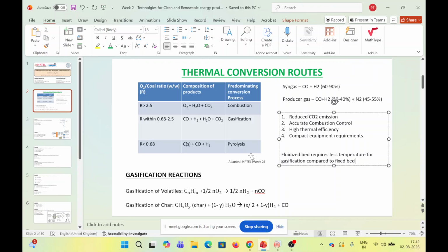This cooled syngas leaves as a substrate, and the energy that is absorbed by the water is taken, that hot water is taken to a high pressure steam boiler where the turbine again rotates to produce the electrical energy. So two methods: one is the quench mode of operation and another one is the boiler mode of operation.